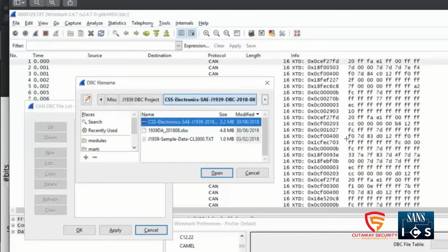Mm-hmm. So with 3PO that you mentioned earlier, one of the 1-page lab walkthroughs that we do at conferences is one where we send out a brake fluid level message where we already know what the value is, and we give that 8-byte value to the people who are trying to do the lab. But there's another one where we've got the keys. We hit the unlock button as we're capturing traffic. So start recording, unlock, stop recording, and then we inch in from both sides and keep replaying it. When we replay it, it will unlock the door because the devices are just responding to the messages that they're receiving. They're not doing any kind of authentication.